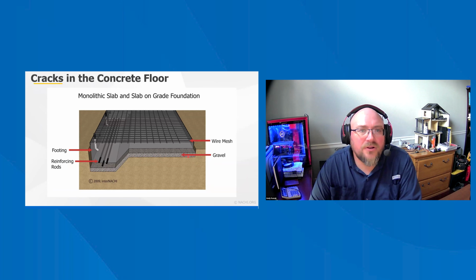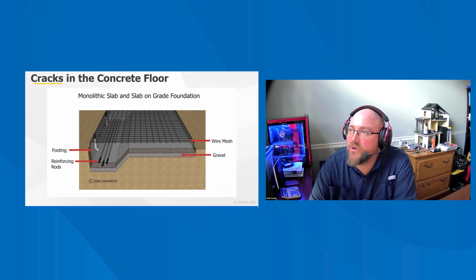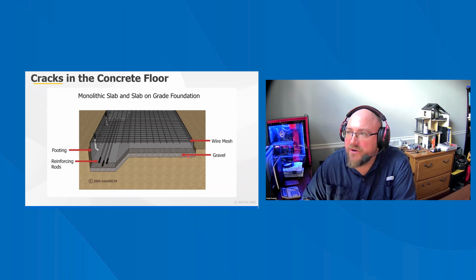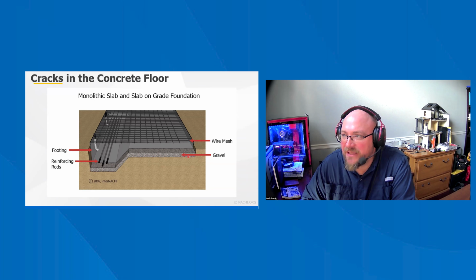Cracks in the concrete floor. Concrete will crack as a normal outcome of the curing process. Cracking can be worsened if uneven bearing conditions exist under the slab, such as uncompacted fill areas. Excessive water used for the workability of cement tends to produce excessive cracking, which can allow moisture to more readily penetrate the concrete slab, weakening the concrete and leading to differential drying issues and cracking. Excessive cracking can allow additional moisture as well as radon gas to penetrate more easily through the slab.